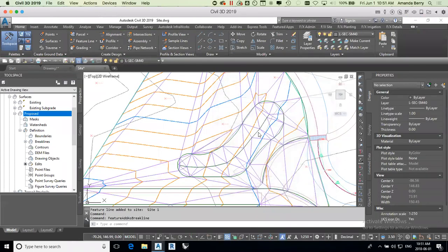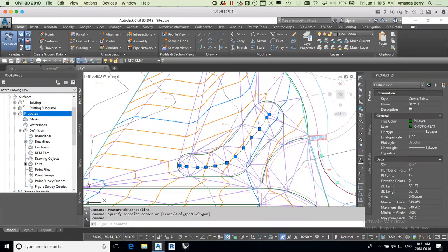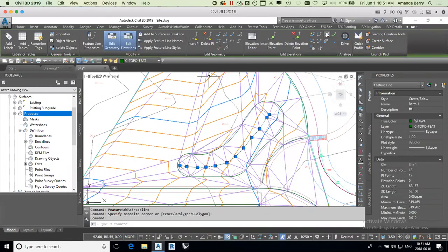There we go. I'm starting to add some triangles in here. I can now say, pop that up a bit. I can grade along here and make this a gradual lift of say 10%.